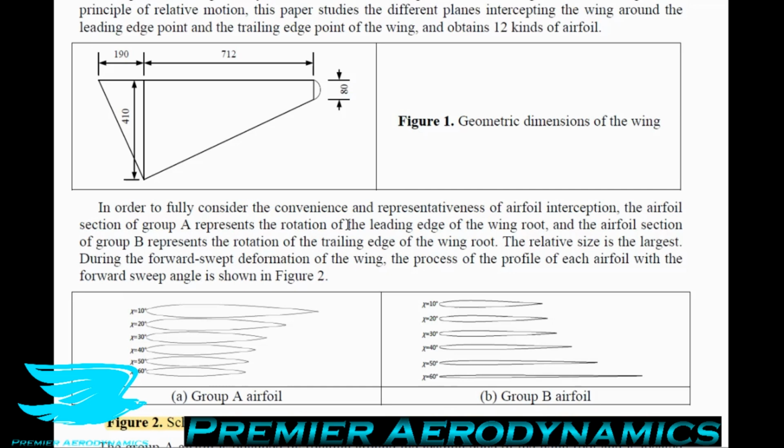And if you look at the figure here in figure 1, it's a little bit easier to understand why that is. And the reason why is because the trailing edge is at an angle. It's tapered the wing, but it's not tapered from the leading edge, it's tapered from the trailing edge. So that means that as you rotate the wing backwards, that trailing edge is going to become more and more horizontal. So as that happens, the wing changes the thickness chord ratio. And then once you move past a certain point, it will then start to become more angled again, just due to basic trigonometry.